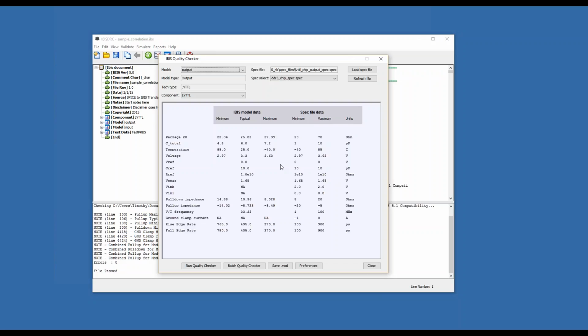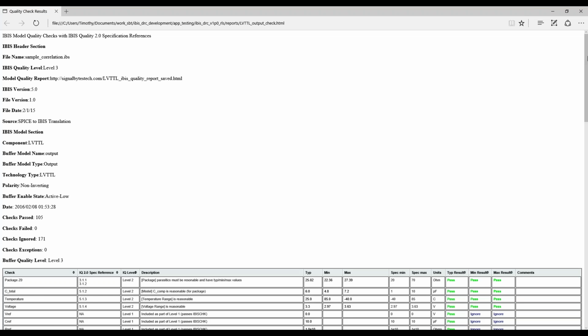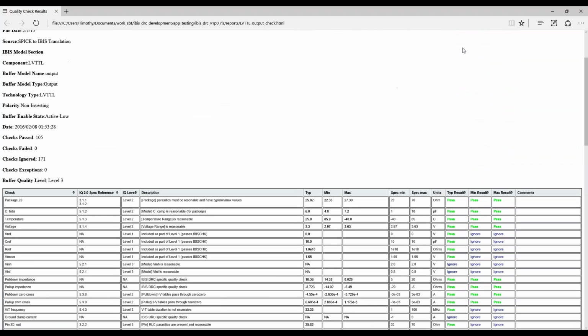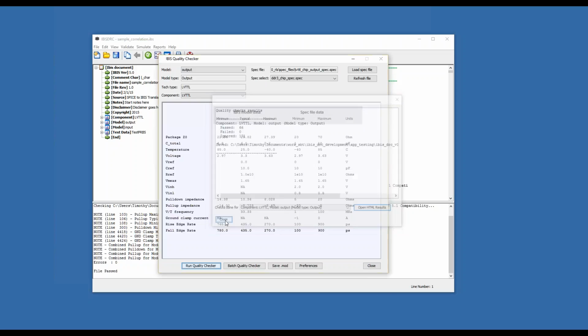And these quality checks, if you saw the last webinar, you've got to automate. There's just way too much in here to do by hand all the time. So you've got to start automating, scripting it, or like I started way back when, start with a manual list and eventually move to automation. You've got to start checking at least some of the major things, like the timing loads and the die capacitance.